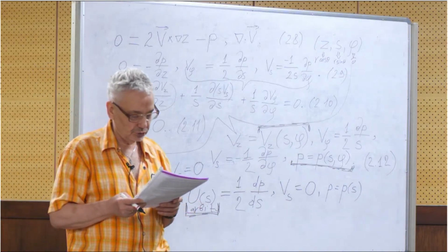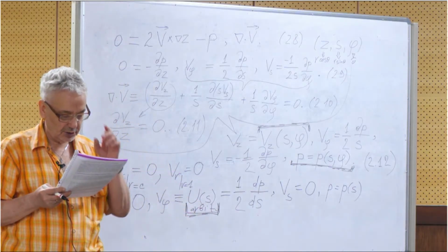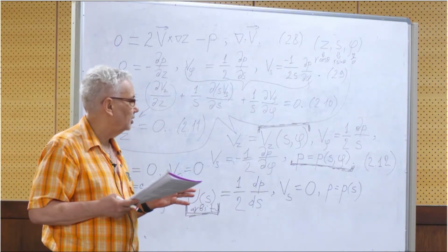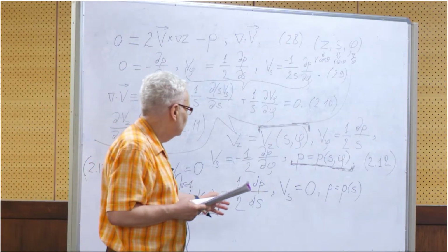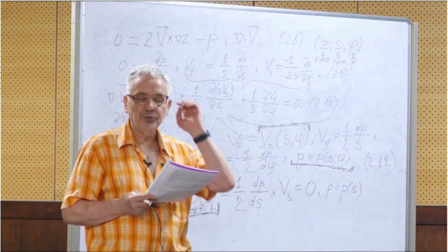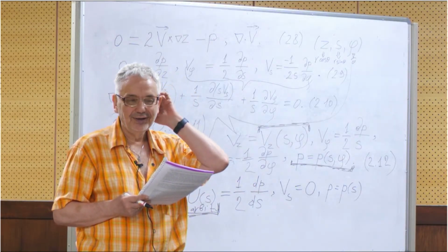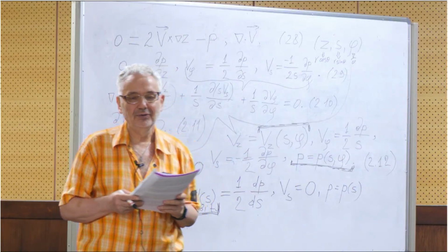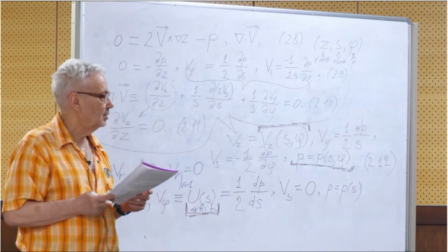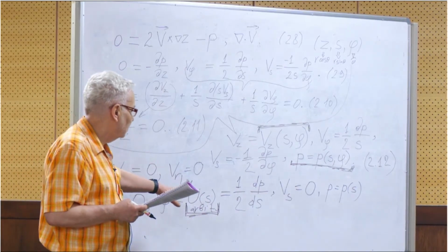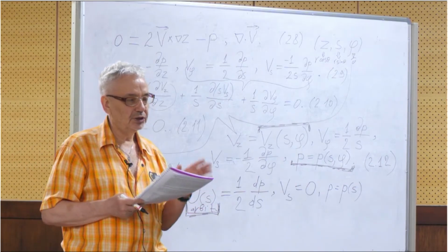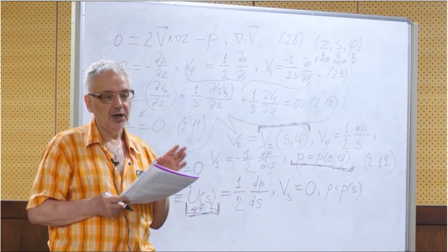You can use not necessarily a boundary condition, but some additional condition just to specify the pressure, and we showed that. And very important, I got what I wanted to say. The important thing is that this extra boundary condition should be applied not directly to the boundary, but to the upper layer.